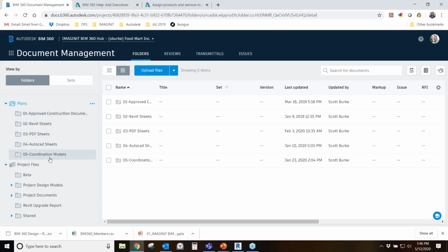I'll go through that in Revit, but just make sure when you're doing this document setup that when you do set your Revit project file up, you never put it in the plans directory. It's not read the same way. It doesn't have the publishing capabilities, so it just breaks it, and that's not good.